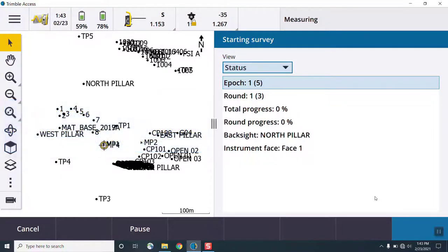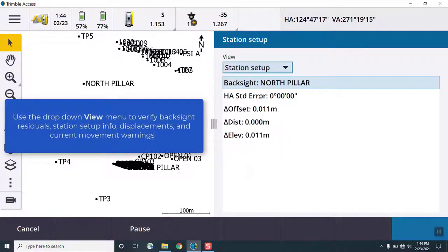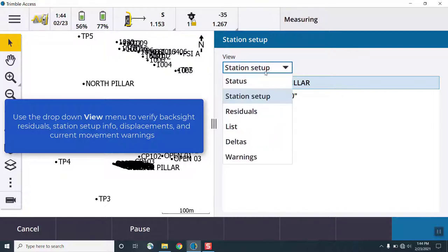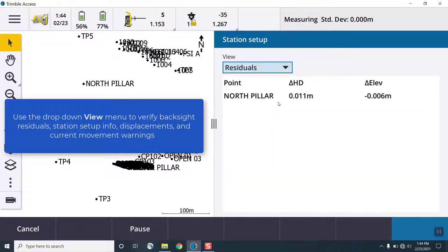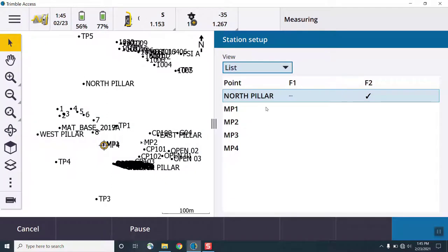There are a variety of other settings for changing how the monitoring will be performed, such as the adjust EDM settings for distance, which will change based on the measured distance and EDM type. There's also the auto measure passive targets, such as DR measurements, where it will automatically measure the target. And as well, we can enable the laser pointer to be turned on while making epoch measurements. The other options are setting the instrument mode automatically based on distance. So this will choose the best measurement mode based on the target distance.